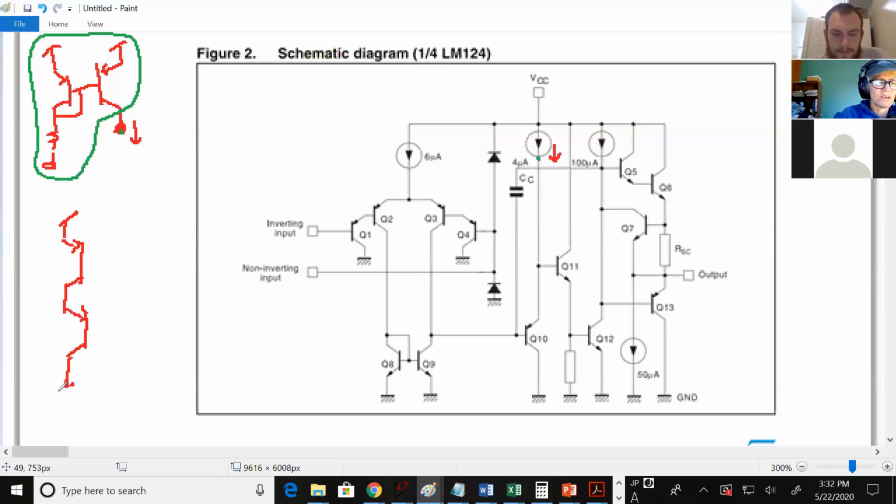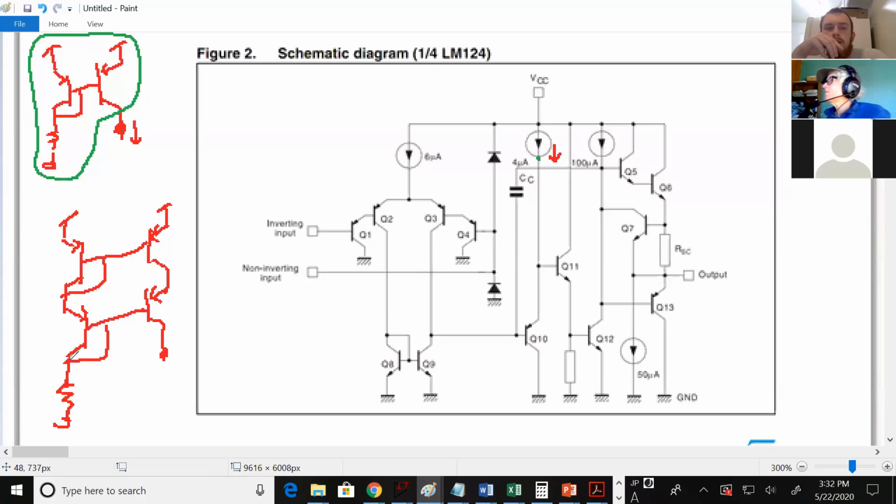Turns out if you cascode the right, you need to have voltages for the bases of both of these transistors. So now this is cascoded. This node is this node, but you need to be able to give the bases the correct voltage. So you often have to do some biasing like that. So it's all about getting voltages for this base and this base.